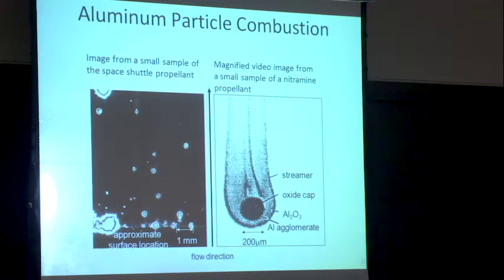If I turn the lights on and look at one of these particles, this is what I'm going to see then. I'm going to see basically the core particle here. If you look closely, there's an oxide lobe here that's developed, and this is now the flame structure that goes around the flame. So no longer do you see this nice spherical flame that I showed you earlier when we were doing the scientific experiments, but because of the convective flow, you see this tail coming off of the surface. And because of the tail, you can have recirculation behind it here, and you can accumulate then oxide on the surface, and you get this multi-size distribution of the oxide products that are related to the original particle versus what's formed in the flame zone out here.